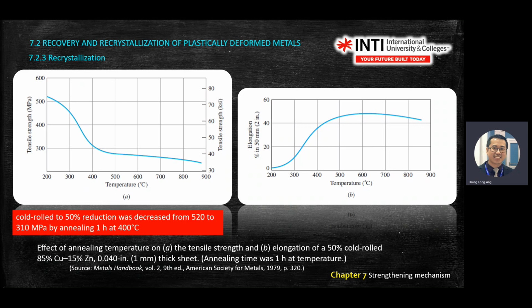If the question asks you to do 2%, then this one also can find yield strength. There are two ways, but there is an error between the first yield number and the second yield number. Okay, because nobody knows where the plastic-elastic transition exactly happens unless you observe under a microscope.